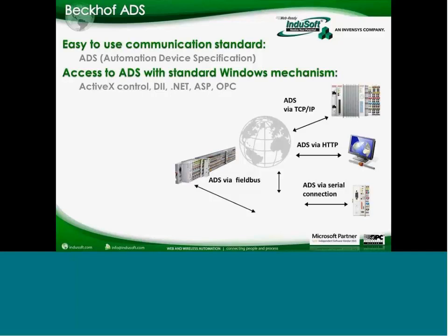The ADS is the one that goes to the field device. So you may say, oh, can you talk to a TwinCAT that is communicating over Profibus? Well, for us, it is transparent. You're going to talk to the ADS. The ADS is the one that's going to go talk to the controller or the IOs and bring us whatever information we request from them. So this allows the communication to be really fast, because you're talking only memory to memory. Talk to ADS, we're going to always get the data there.